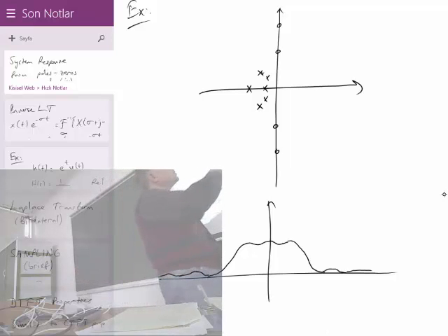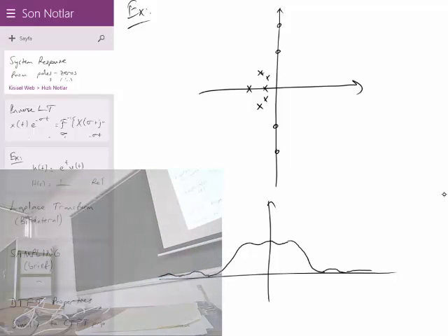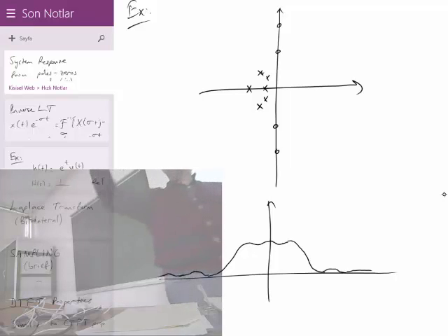If the number of poles and zeros are equal, at infinity these tails will go to a constant level, not 0. It will be a constant c times 1. If the number of zeros is more than the number of poles, then it will diverge to infinity at both tails. In order to suppress them, we must have more poles than zeros, like this one.